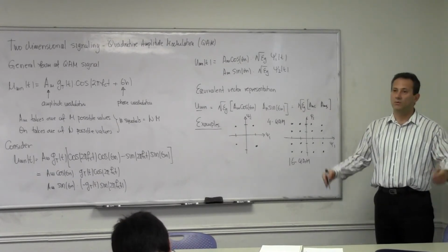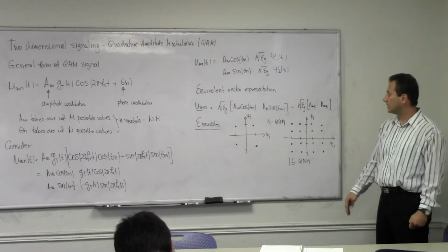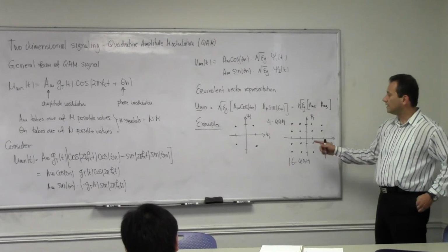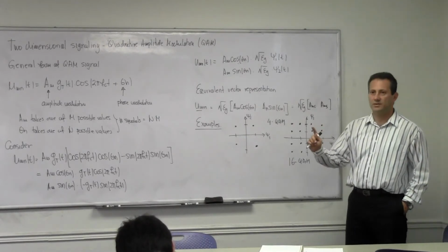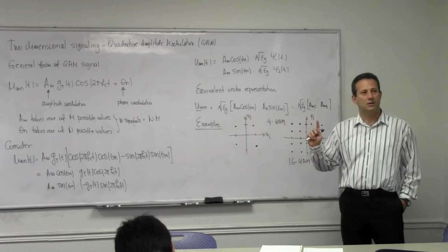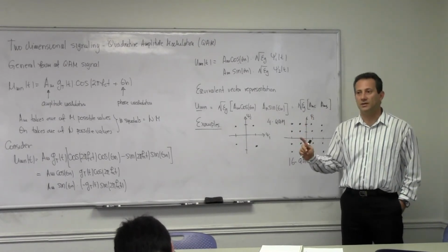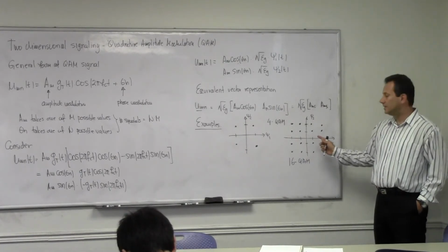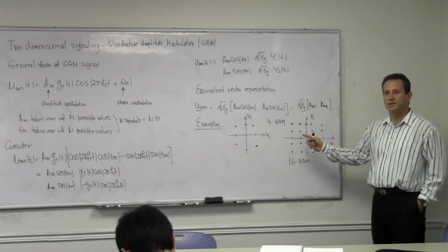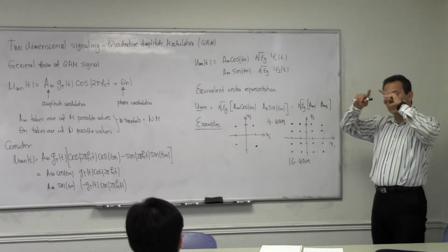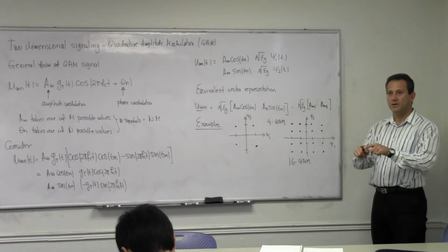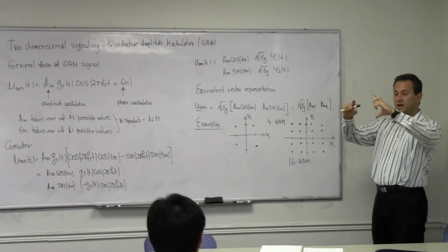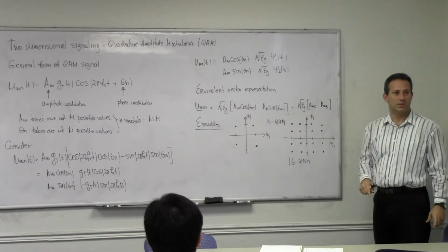And this can go to a lot of points, right? So you can have a lot of points in this plane here. What you find out here is where the major difference is between this and the phase shift key. Here, as you grow the number of points, they are not getting close as fast as in the case of the PSK. In the PSK, they have to be all on a unit circle, right? So as you keep on putting a lot of points, they all kind of become dense. The inside area of the circle is unused completely.